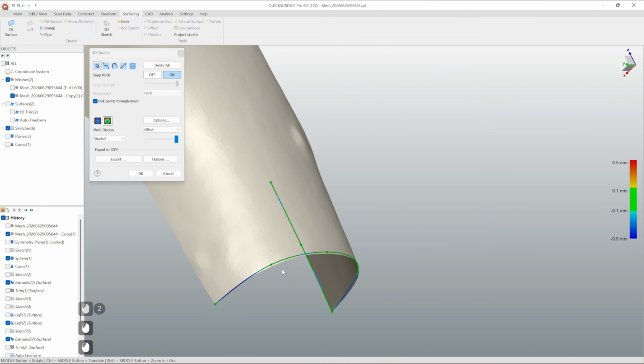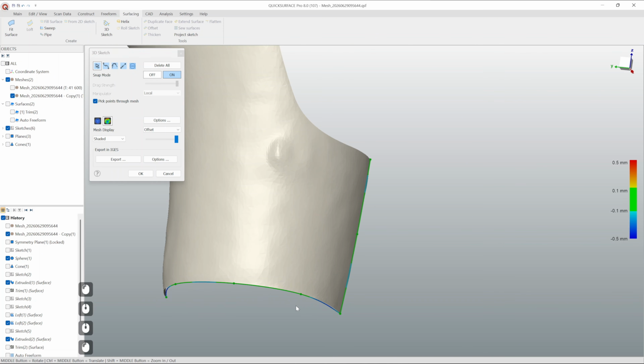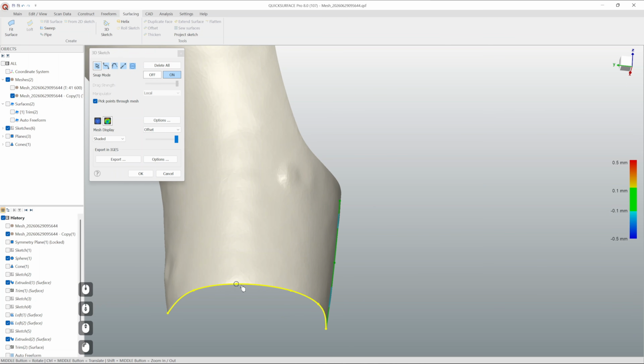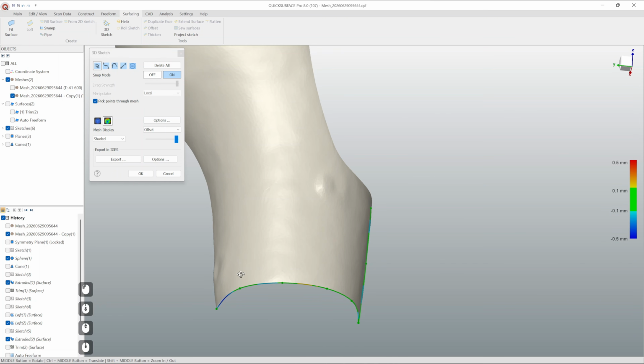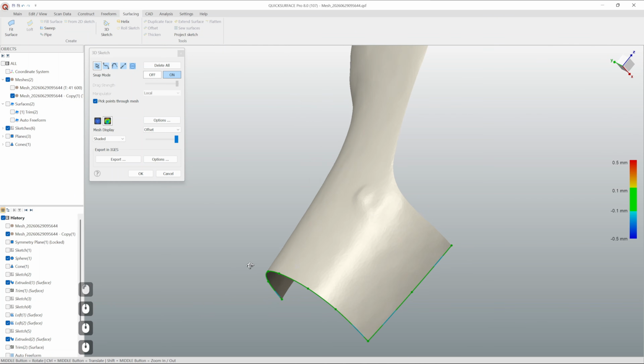Again, I'll just pull it away to snap the edge of this scan data. And now I will try to move control points to make it closer, but from here I can see that most likely I will have to introduce more control points. To have more stability and to be closer to actual scan data. Okay, so let's say this is good enough.